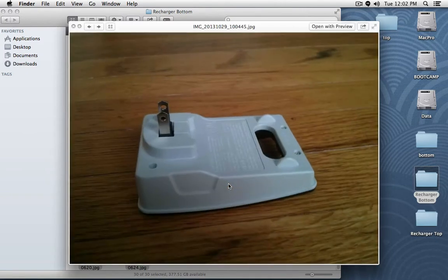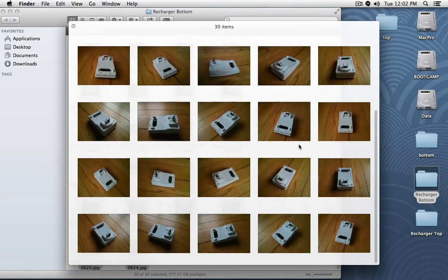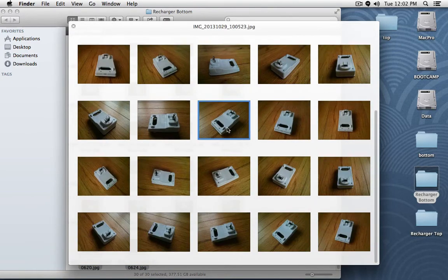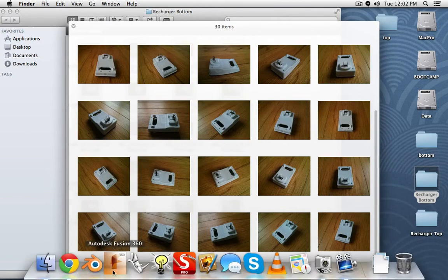You can have a drop shadow or something like this, but try to prevent having really dark areas. Also, try not to stand in front of a light, because then you can cast a shadow onto the object, and that will confuse the software as well. This object currently is white, and my scan actually worked somewhat okay, but if you want to furthermore help the software, because you're going to digitize a full model,